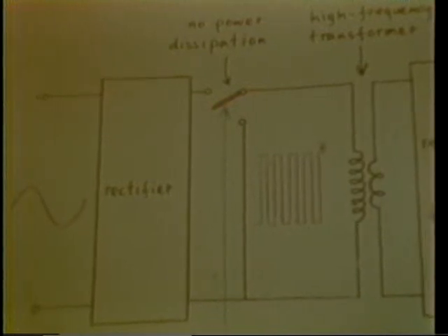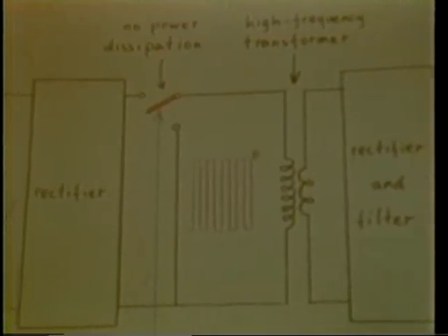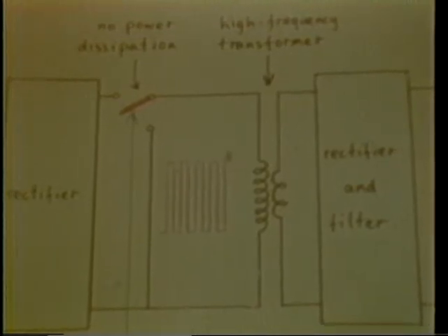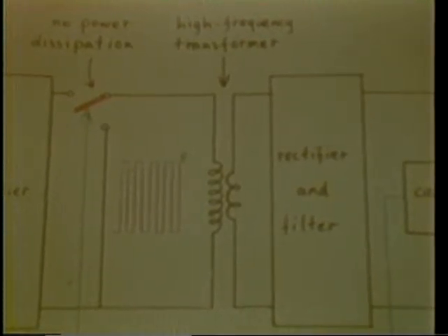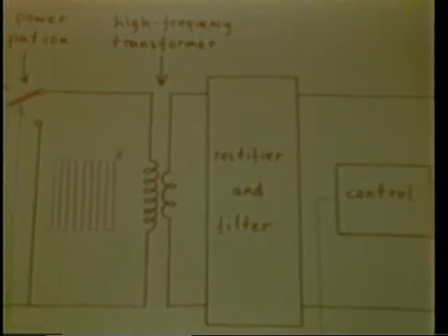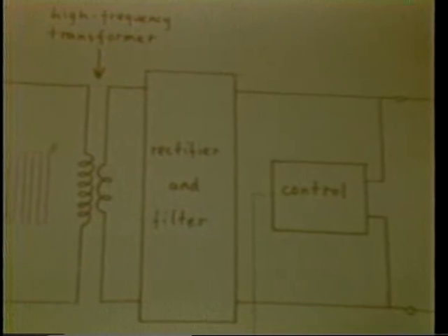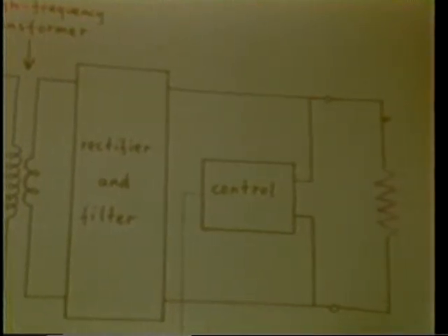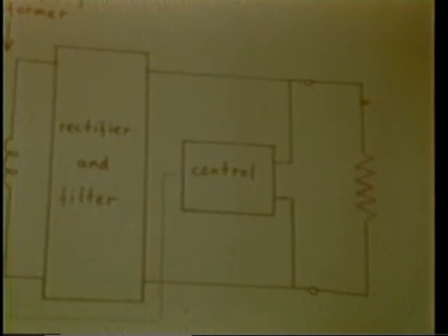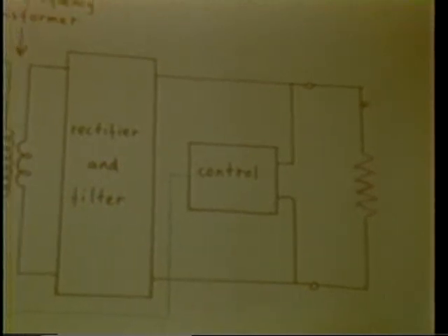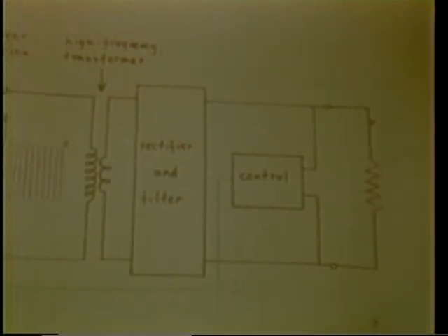So as a result of that now, the modern way of achieving DC to DC conversion, for example, the 110 rectified input down to the 5 volt, is that you now rectify at the high voltage end, and then put the switch immediately after that, and operate the switch at a high frequency. Now it's 20 kilohertz at least and on up, instead of the 60 hertz. So now you can transform down with a much smaller physical transformer at the high frequency than you could at the 60 hertz frequency. And since you get this regulation function almost for free, then that is the final step in the output. So this particular kind of power supply is known as an offline switcher.